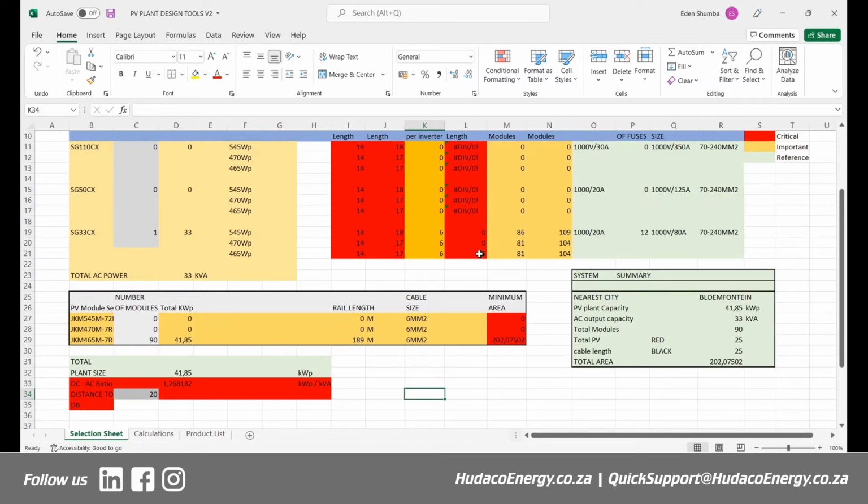The day it's going to be cold, those panels will produce higher voltages than on an average day. Now, what will happen is the voltages will add up because it's a string. And when they do, you're easily going to surpass the recommended value for your inverter. And probably that will end up in the damage of your inverter, and you lose your warranty and every other consequence that comes with that.